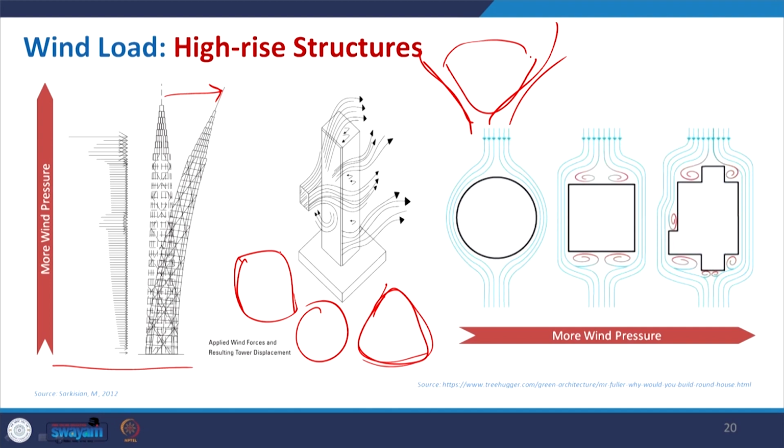So, if I just consider this is my building, a high rise building, in order to depict it, I just fix it like this. For the wind, this particular end is basically acting like a cantilever to the base. So, it will move much, and where your base to height ratio is too much, it is considered to be a tall building, and the effect on the top portion of the building is high. So, for that we definitely need to make some structure which will resist this kind of lateral load.